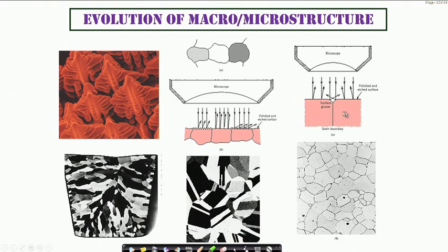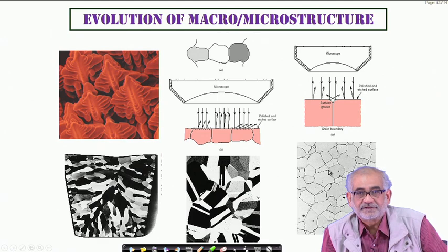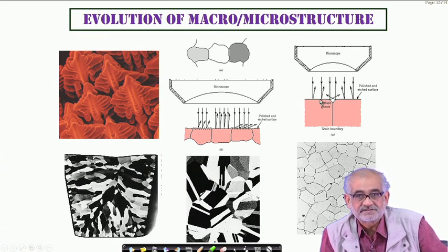So when we go through such metallographic preparation, we adopt a technique called etching, which is a selective chemical dissolution of the phases depending upon their electrochemical potential. And since the electrochemical potential of these boundary regions is higher than that of the grain body, they dissolve faster. Now when you expose such a structure under the microscope, which also has a source of illumination, the light falling on this surface will get uniformly reflected from the region which is less affected or less chemically attacked, and hence will be more lustrous and bright.